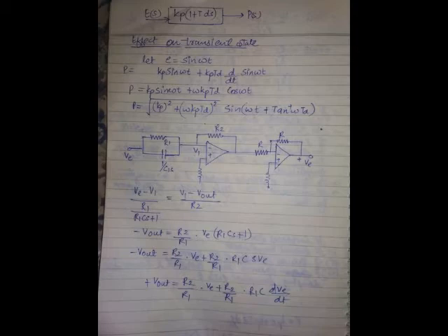Now, adding a phase lag compensator is adding a pole or adding a zero? Pole. Adding a P plus I controller is also adding a pole, because if you look at the transfer function of a PI controller, KP TIS plus KP by TIS, first there is a pole at the origin, and after that on the left side there is a zero. So what is the dominant element here also? When you add a pole to a system, what is the effect on stability?